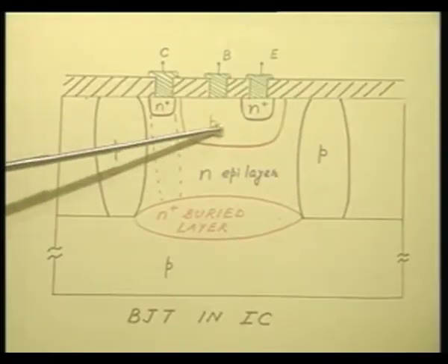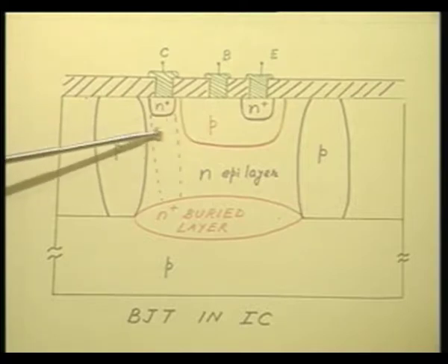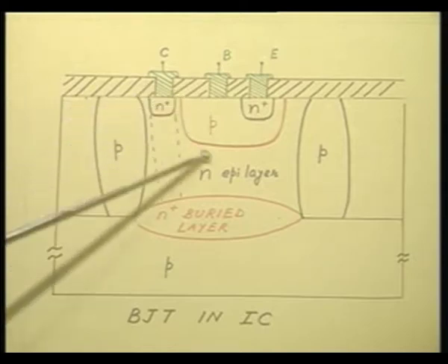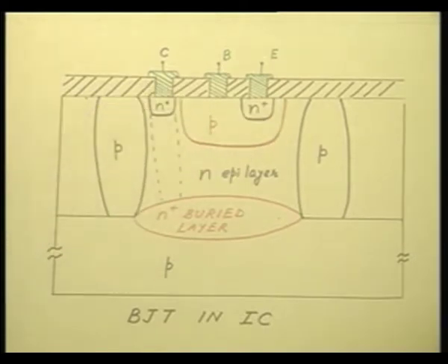How can you suppress it? By suppressing its gain. How do you suppress its gain? By increasing the base width. This is a lateral transistor PNP. So, this is its base, right. That means, the base of your actual transistor should be a considerable distance away from the isolation p-tub in order to keep the base width of the parasitic PNP transistor large.